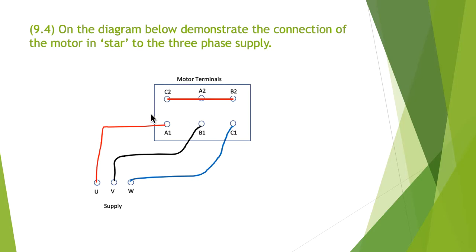Motor terminal boxes are very well set up. They're always set up in this configuration, allowing you to put links straight across and connect like this for a star. If you need to go a delta, you can just connect the links vertically.